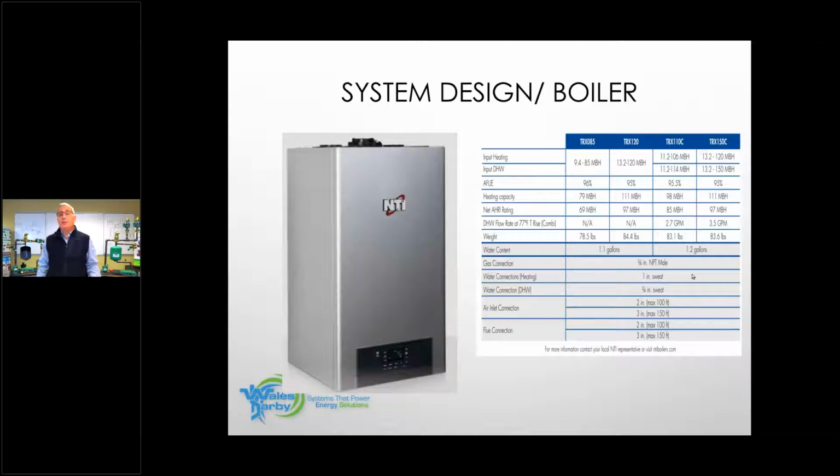we decided that 14 degrees was our average coldest day of the year. But what's really important to understand is we don't always hit 14 degrees every day of the heating season. Our heating season here averages about 6,000 hours, and we average about 2,500 hours where the equipment is actually running.